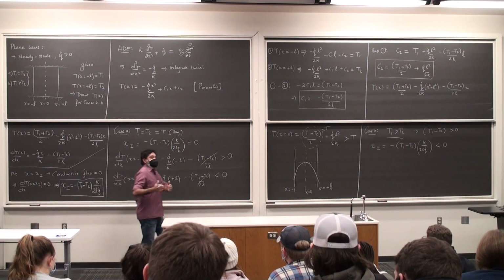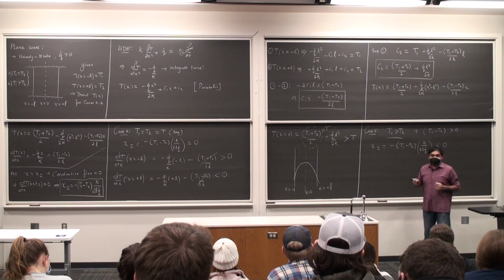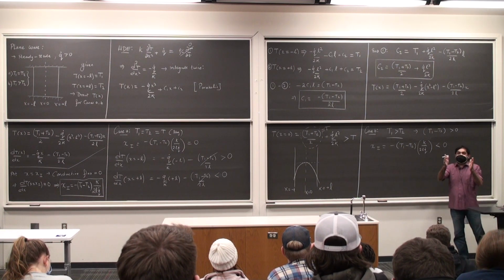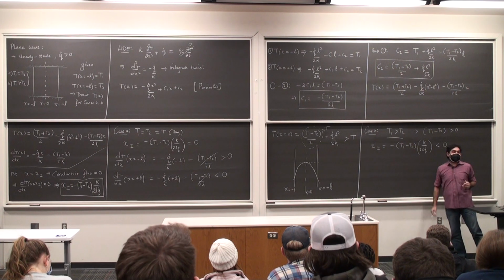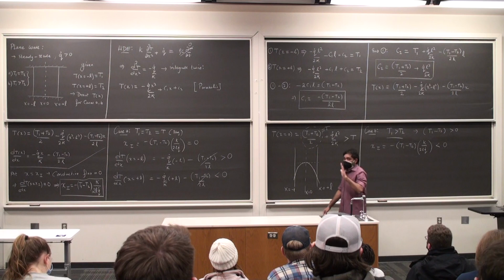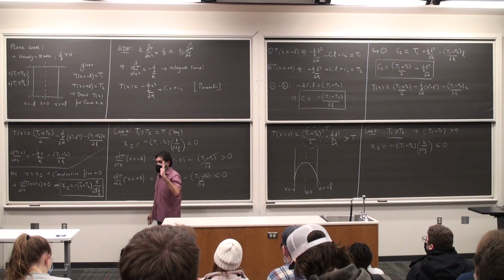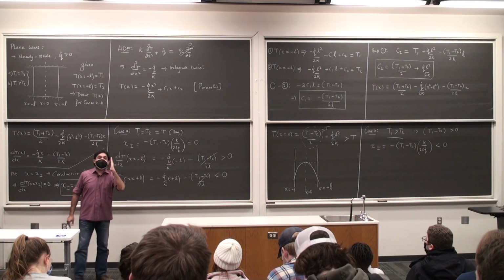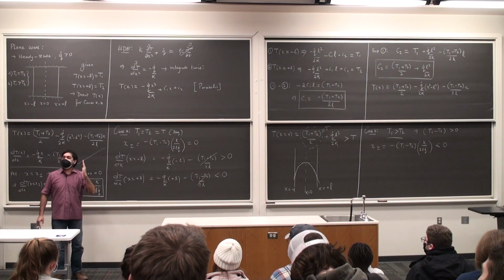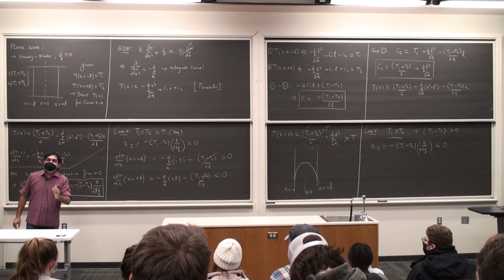If T1 is much larger than T2, I can end up with a situation where the magnitude of this number is going to be greater than the magnitude of the length L. So there is a possibility that my location where the conductive flux is 0 is not physically present in the wall at all, because of the range of T1 and T2 values, which is the type of profiles that you have seen in the previous lecture.